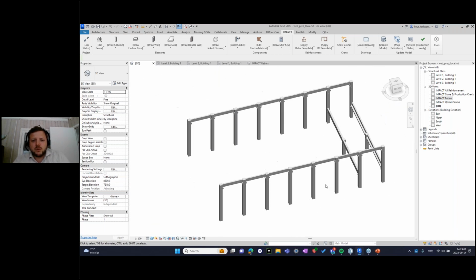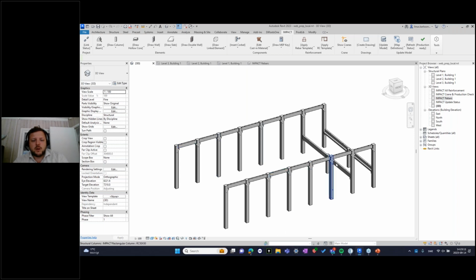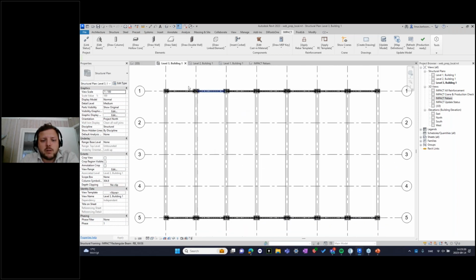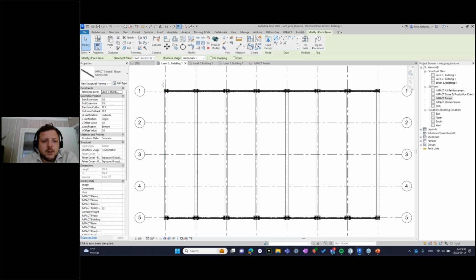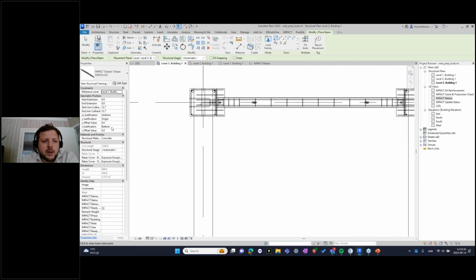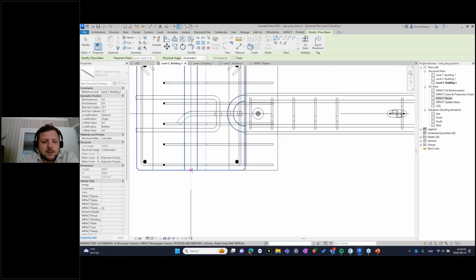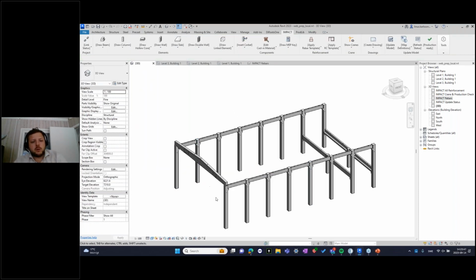So the next part I was planning to show you is to add the SIBs, so the sloped I shapes on the top, and we are gonna use some pre-stressed beams here so that we can see the strands as well. So I'll start to draw beam and then switch to pre-stressed. Select my section type, and here it is. So I will do it a little bit differently here because now I will just draw one of them. So something like that, looking like this, pretty okay.